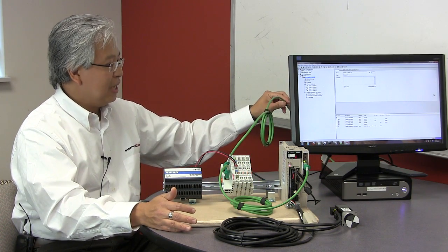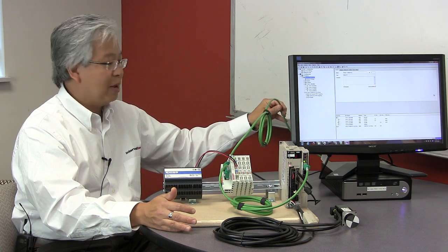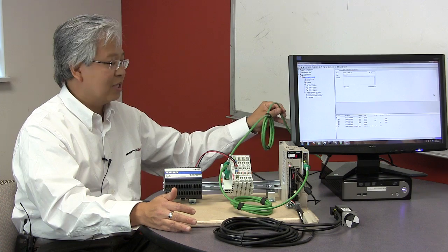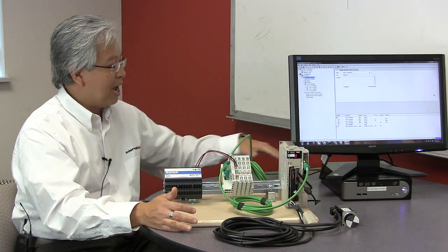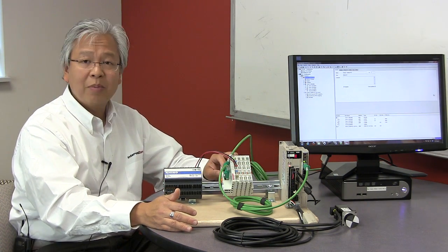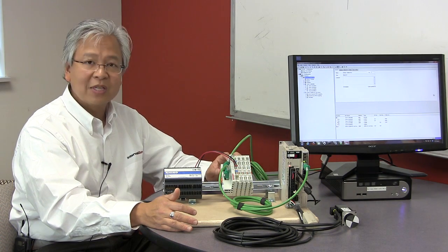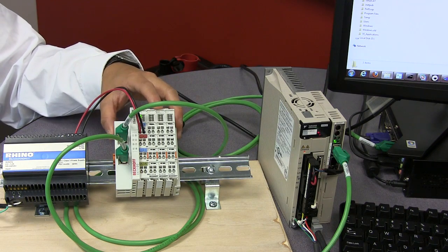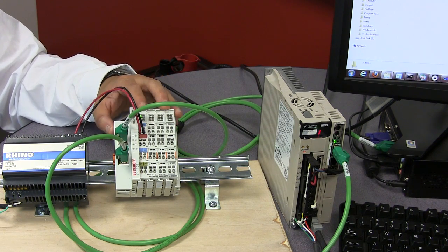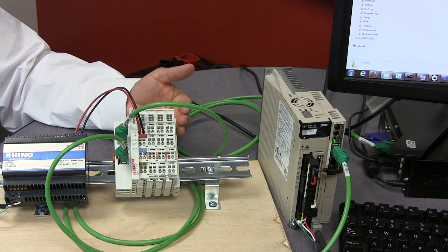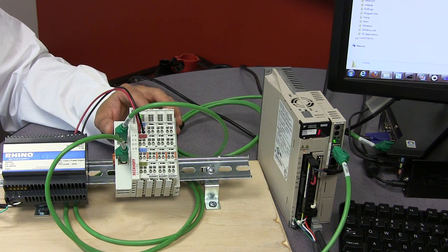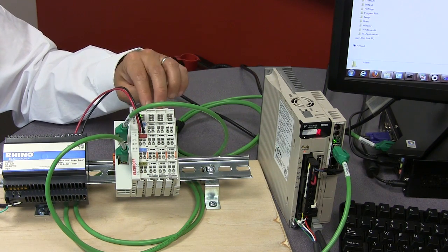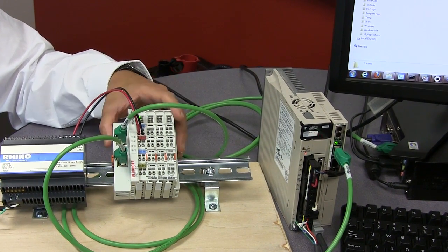If you see here, one of the benefits of EtherCAT is that we're able to use standard Ethernet hardware. There's no proprietary cabling. This is just a simple Cat5 cable coming out of the PC and into the input port right here of our first EtherCAT module. So we have one cable coming here. Here we have just a couple input and output modules. EtherCAT is very expandable. This bus can be expanded up to like 65,000 nodes, so it can definitely scale to some very large applications. Here we just have a couple for this desktop example.